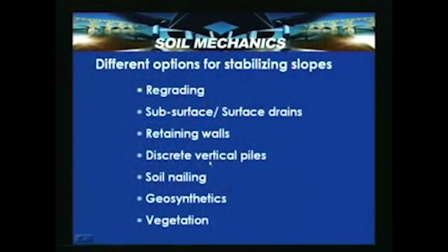In this method, the load arising from the moving soil mass is transferred to the piles into the deeper stratum. This method can be adopted for new construction, or for an existing, predominantly soil slope, to stabilize it.